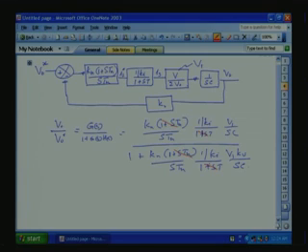Again if you write down the transfer function, in the denominator an S square term will be there, but the S term, the damping, will be missing. So if you use the pole zero cancellation here, this system will become unstable. So we want to keep this controller so that steady state error is 0 and we have a good bandwidth. Now how do you choose our Tn and Kn in this case?